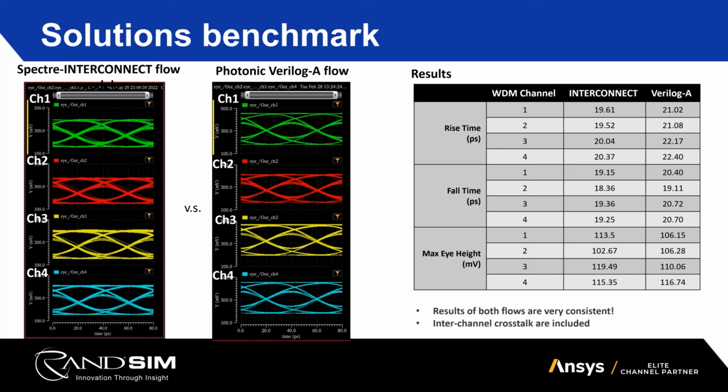Right now, we also added a new feature to the Verilog-A platform so that it can also characterize the channel crosstalk. So we see that the interchannel crosstalk is included in both platforms, and the eye openings are pretty comparable. So overall, they are basically very consistent results in the two different platforms. So users can choose the best platform for their design purposes.